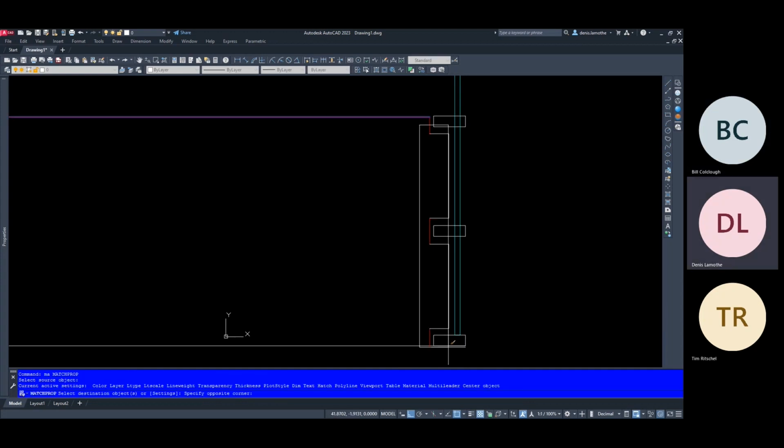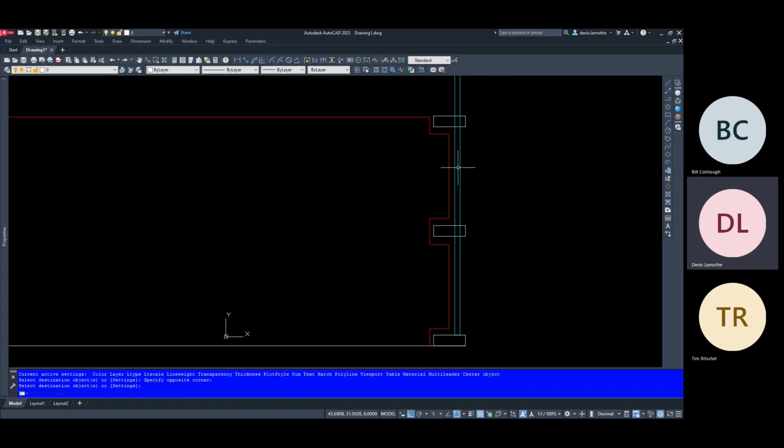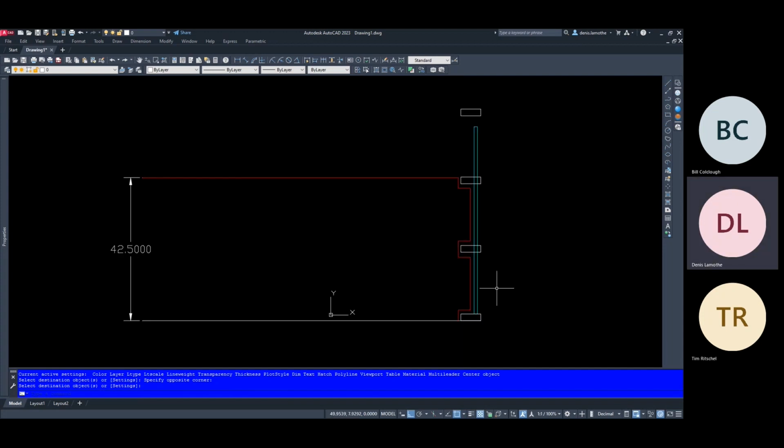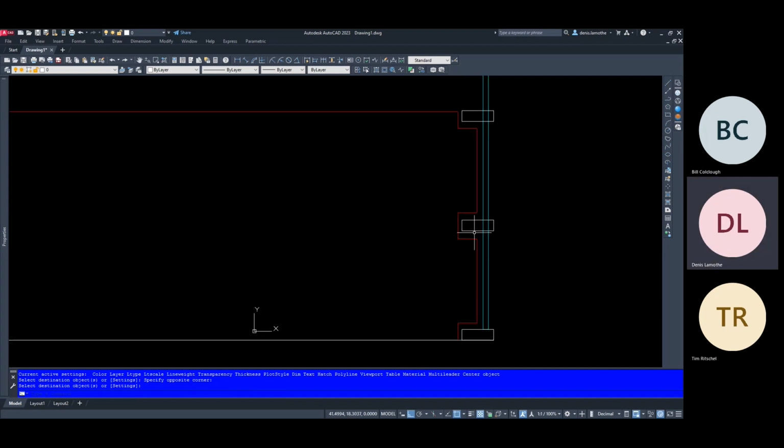Hopefully that clarifies a little bit what I'm talking about here, where there might be some exceptions. It could be a curtain wall. There might be, I don't know, a wall with some kind of shelving on it. Maybe there's a built-in box for a display case or something. Regardless, if there's any situation along our guardrail that would create an opening of greater than 4 inches, we need to make some kind of adjustment to make sure that we have less than 4 inches.